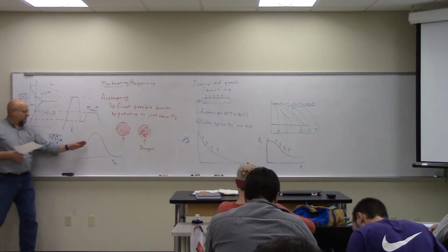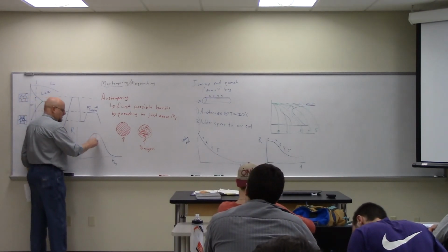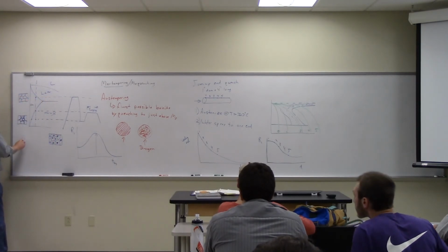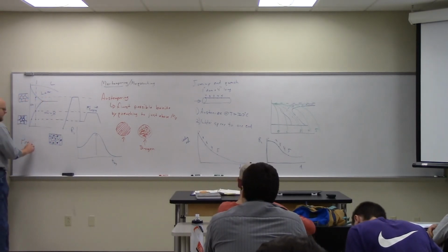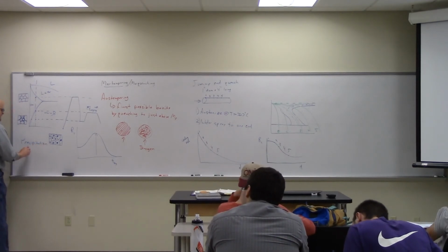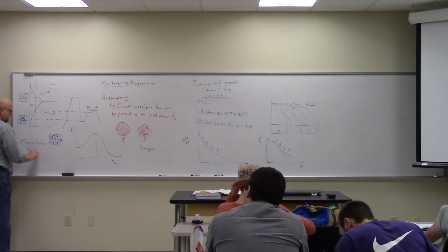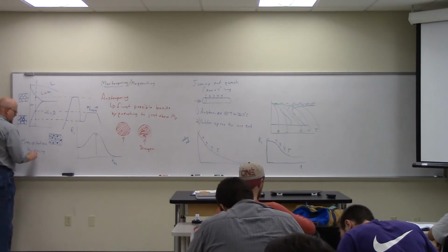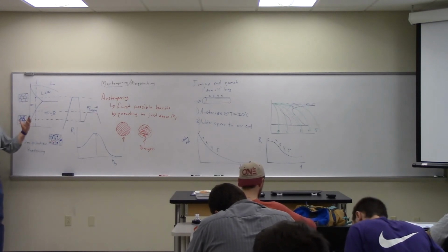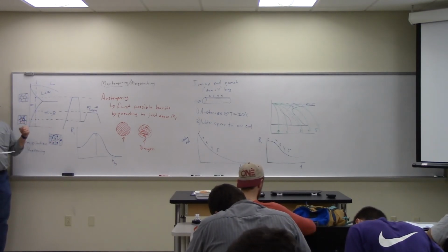But the point is just that there's a target here. I want to get this peak. That's what I want to get. I'm going to call this process precipitation hardening, because we're forming these precipitates in the matrix that, again, serve to inhibit the motion of dislocations.